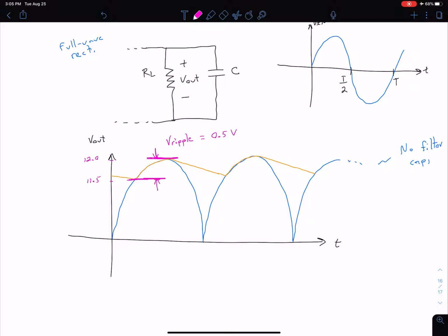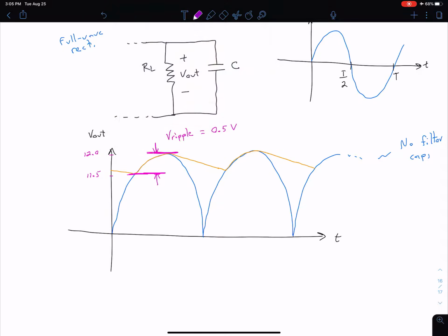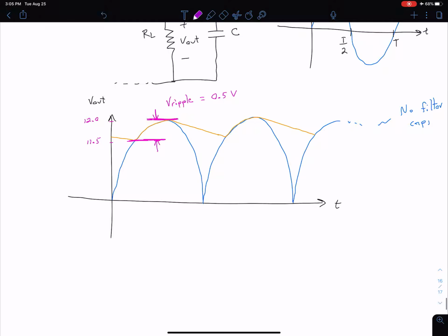The other important thing that we can label here in this circuit is related to our frequency. So if we pick a point, so let's say this point, we can say that occurs at this time, and we look for the point where that's repeated, so that would be over here. So the difference between these two points would be 1 over our ripple frequency, because again, remember, our period is just 1 over frequency, so 1 over our ripple frequency. And let me draw that maybe a little clearer here. Let's do 1 over f ripple.